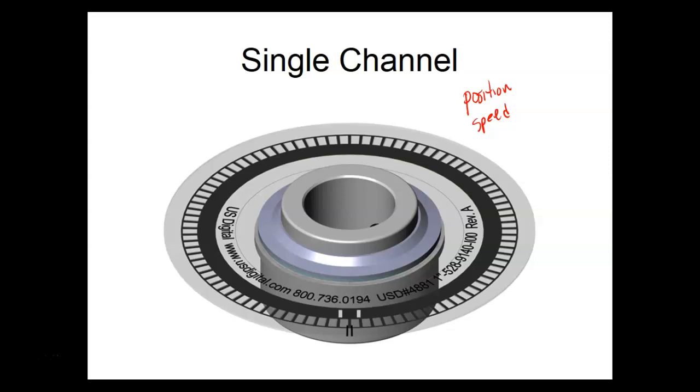So the rate of these pulses, every time a blade comes by, we would get a pulse, and the rate of the pulses would be directly proportional to the speed. So as the rate goes up, the speed's going up. If the rate goes down, speed goes down. But the problem is that when we talk about rate, we're going to use something called frequency.